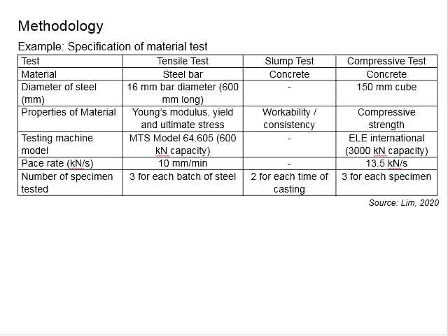Then you can estimate a maximum capacity of the sample. Then you choose an appropriate machine within your laboratory to have your anticipated capacity of the sample falling within the range of 50 to 80% of the capacity of the machine. This should be able to give you the intended significant figures for your results.